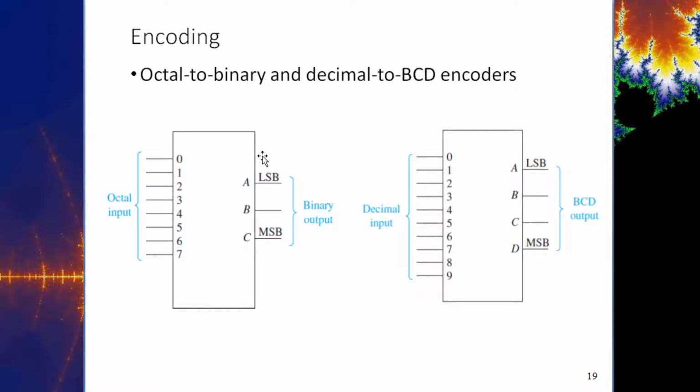When I think about encoding, my mnemonic device is that it enlarges to a coded output. Decoding devolves into one output, encoding enlarges to a coded output, right? So if the number 4 gets activated here, the fourth one, then that's going to be 100, most significant bit, 100.